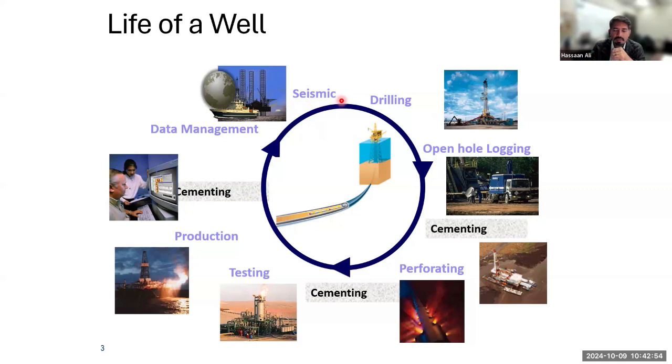In the seismic survey, there is a specialized equipment that is deployed, which will shoot these high frequency sound waves into the earth surface. And these high frequency sound waves will travel the earth's surface and they will bounce back. That bouncing back will depend upon the density of the soil, density of the formation. Some formations which are tightly packed, which are very dense, not very porous, will have a better return. Some of them which are highly porous will have a poor return. So you will be able to plot at different depths what your formations are. You can determine where your topsoil is, where it ends, where your shale starts, where your aquifers are, your water and different type of stones like your sandstone, limestone, and you will be able to very accurately plot the formations and depths.